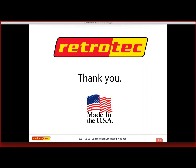There's no maximum about tubing. Tubing is a pressure element, so you could do it. There is a slight delay that happens when you get to like 1,000 feet of tubing. But in general, if you're going to do all the way across most of the warehouses or something like that, that kind of tubing is a minimal impact upon your test.